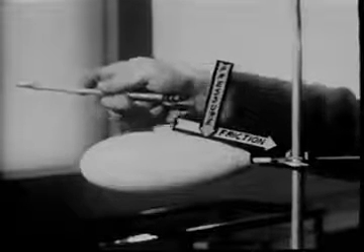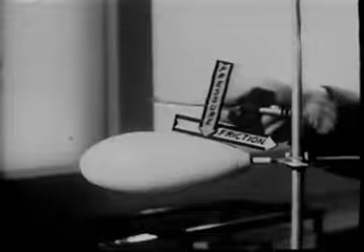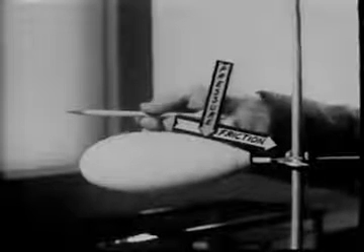Adding up all such components for all elements of the body's surface, we get two contributions to the total drag: pressure drag and friction drag. Friction drag is always present because all fluids have some viscosity, but the pressure drag may be either very large or it might be quite negligible. Which it is depends on the difference between the average pressure on the front half of the body and the average pressure on the rear half of the body.